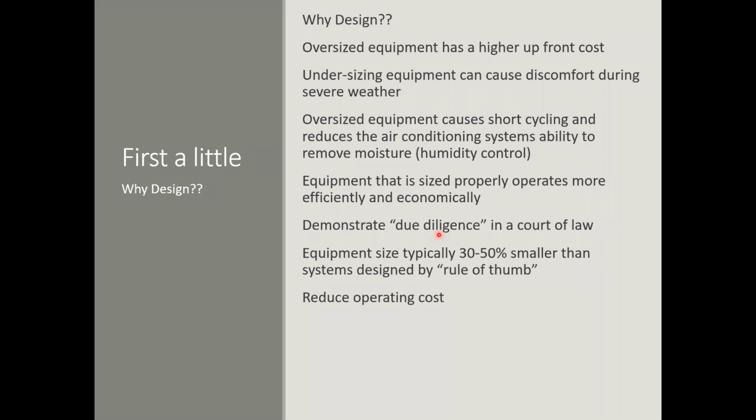Or would you rather be able to say, well, actually, I did a very detailed Manual J calculation that gave me my calculated heat gain and my calculated heat loss. Knowing that, I was putting in a gas-fired forced air system. I was able to then use Manual S to decide which of my gas-fired furnaces had the capacity to meet my calculated loads.